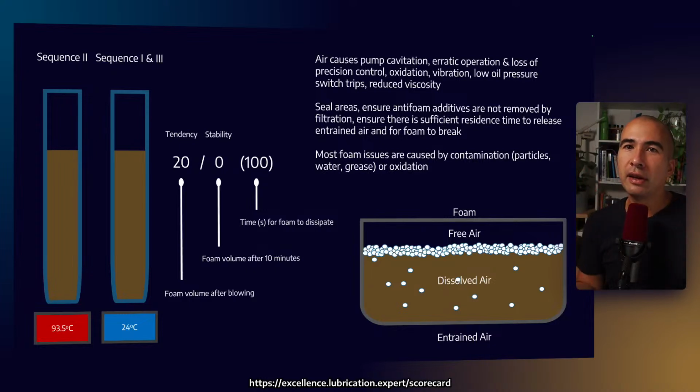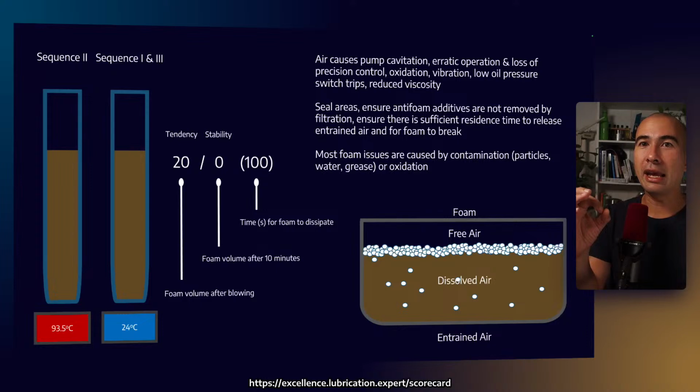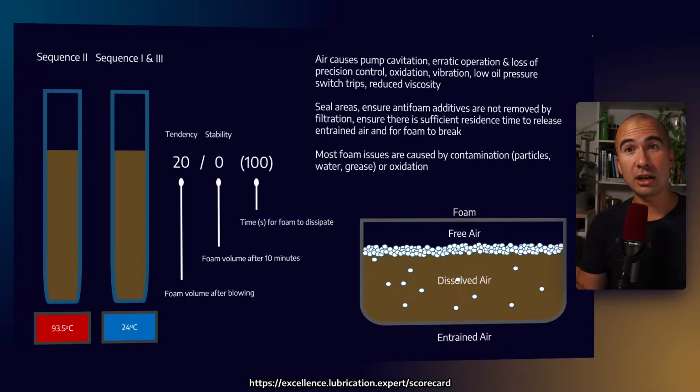In actual fact, I would say it's the entrained air which is the most problematic, right? Entrained air, if it gets sucked into a pump, can cause cavitation issues.